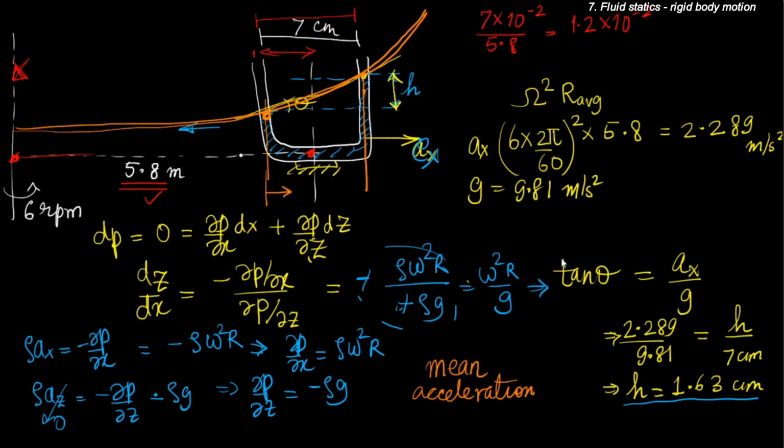So essentially, this assumption is like a rectilinear motion. So this assumption says that the surface of the air water interface will be a straight line. That is, if we had a beaker and we accelerated, in this case the acceleration is in the opposite direction, the centripetal acceleration, the surface is something like this. So in the first result, when there is a mean acceleration, this is assumed to be a straight line.